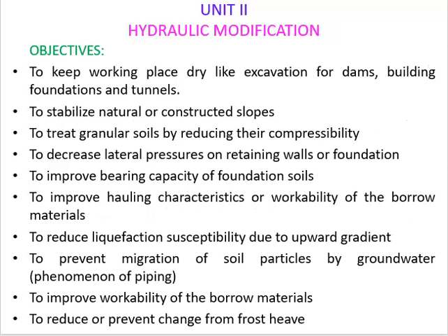Objectives of hydraulic modification technique. The main objectives of hydraulic modification are to keep the subsoil dry for foundation works, to accelerate the consolidation settlement so as to reduce the post-construction settlement, to decrease the pore water pressure and increase the strength.